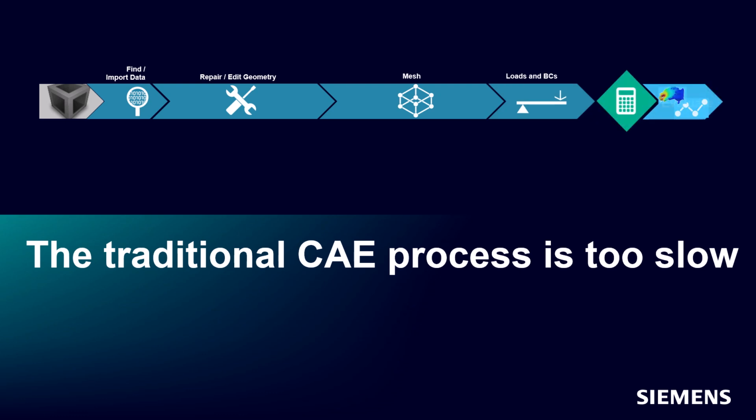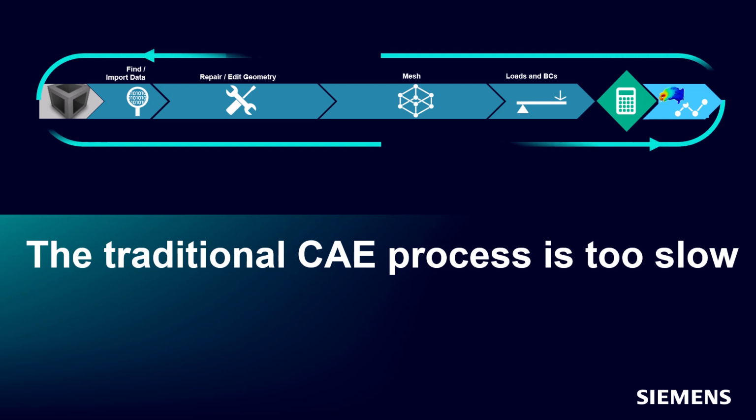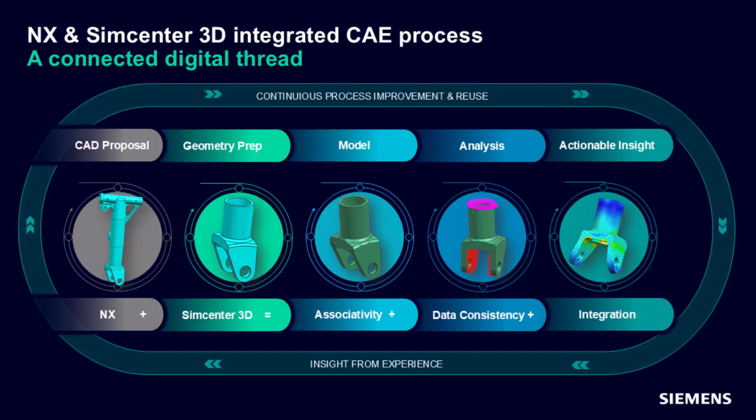At the first stage of the process, and after the initial CAD design is available, structural analysts need to edit the geometry for simulation purposes. However, transforming and preparing the CAD geometry for simulation is a very time-consuming and often manual process, taking up to 20% of the analysis modeling time. But what happens when the design changes? Using today's processes and tools, engineers now typically need to repeat the entire modeling process again from the start.